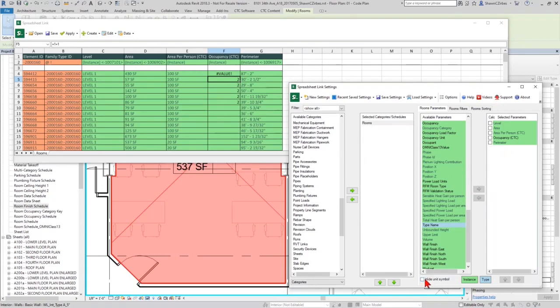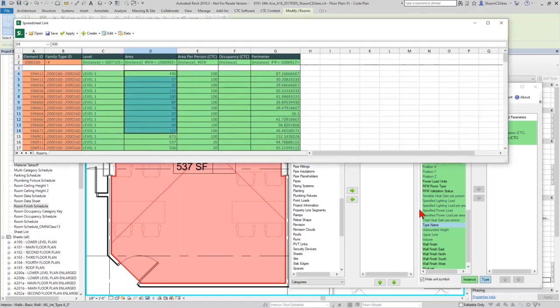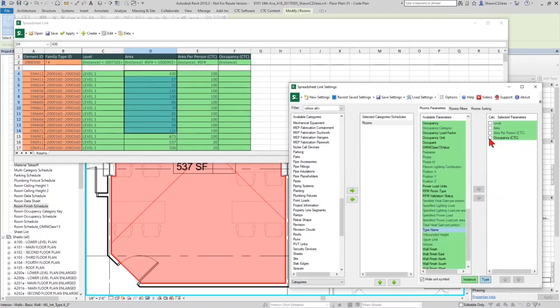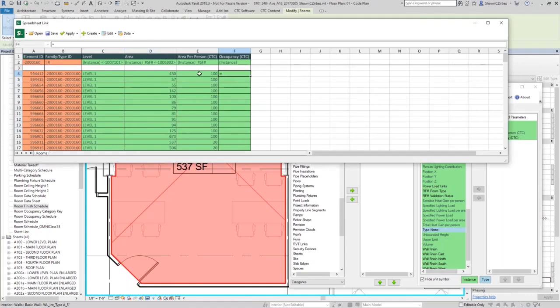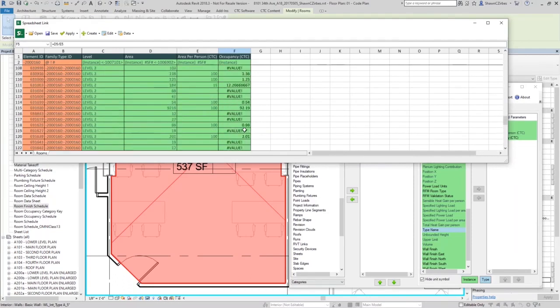What I like to use is this little hide unit symbol down here. We've built this in to automatically strip away the units of measure. It writes them at the top so you know what they were, you know what to expect from them, but now you've got raw numbers that you can play with, right? And we've also built in this little calculate thing here because I don't feel like filling a formula out and then auto-filling it down. I want this to automatically take care of itself. So I'm just going to go over here and say equals this value divided by this value, and when I hit enter, it auto-fills for me all the way down to the bottom of however many elements I have in this extracted list. Now you might notice a bunch of these pound values or hashtag values out here.